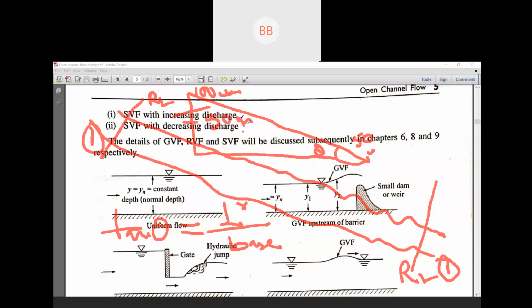Understood, Stephanie? Yes, sir. Then we are going to measure this distance from section 1 to section 2. What is the particular distance? We consider it as the base. Suppose 100 meter. Then when you find out the slope, that is tan theta, it will be 50 by 100. That will give you the approximate slope of that particular channel.